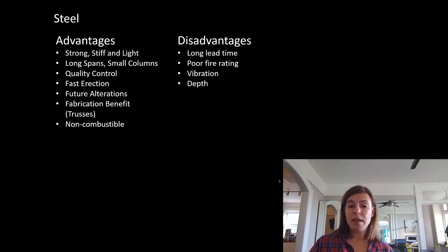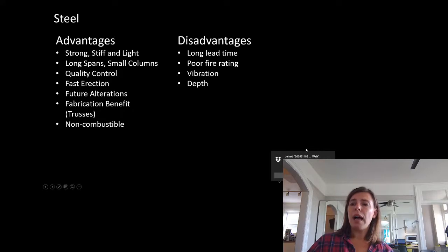And then the base building engineer looks at the shop drawings, and then it's really easy to see if something doesn't match the structural drawings on site. It's a lot easier than picking out those pieces of rebar that aren't in the right spot. You can look at a steel beam and say, no, that doesn't seem deep enough. That looks like it's the wrong beam, or you don't have enough bolts or bolt holes in that right there. So steel has really good quality control.